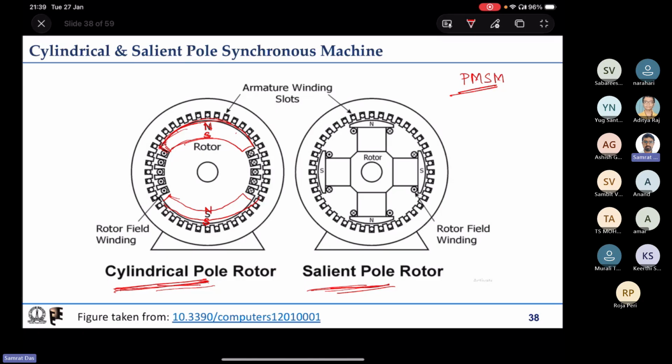So we are eliminating slip rings if we have permanent magnets on the rotor, and if that rotates at the synchronous speed, then we create a rotating magnetic field that is stationary with respect to the stator magnetic field. Now what else do we save? You can see that a permanent magnet inherently has magnetism, so it has magnetic energy, so it is a source of magnetic field.